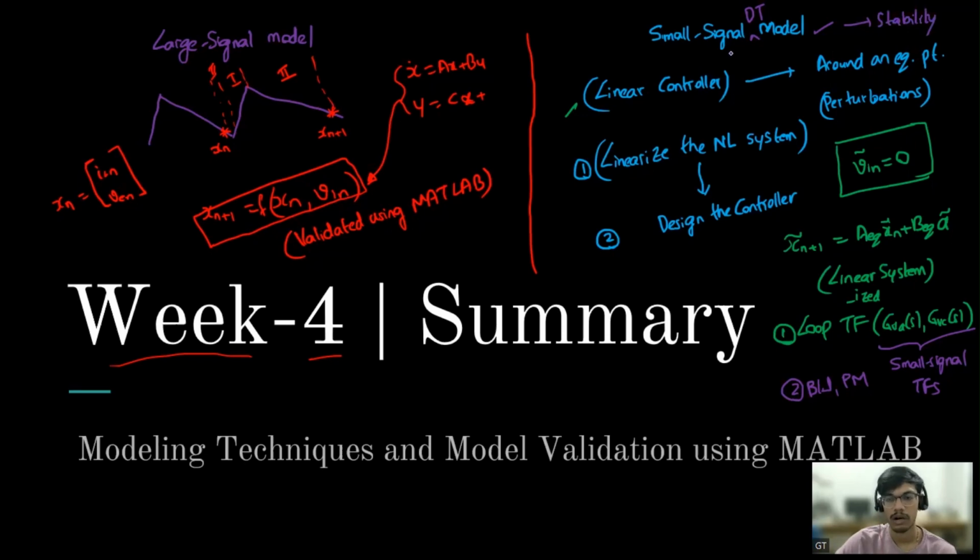So for that reason, to get the exact stability and other phenomena of the converter that I want to know, I am designing the small signal discrete time model, so that the ripple information will be present in it and I can get the exact stability information. Whereas in the case of continuous time, it is an average, right? Switch averaging method, or whatever method they are using, will not contain any ripple information. So we are losing the ripple information.